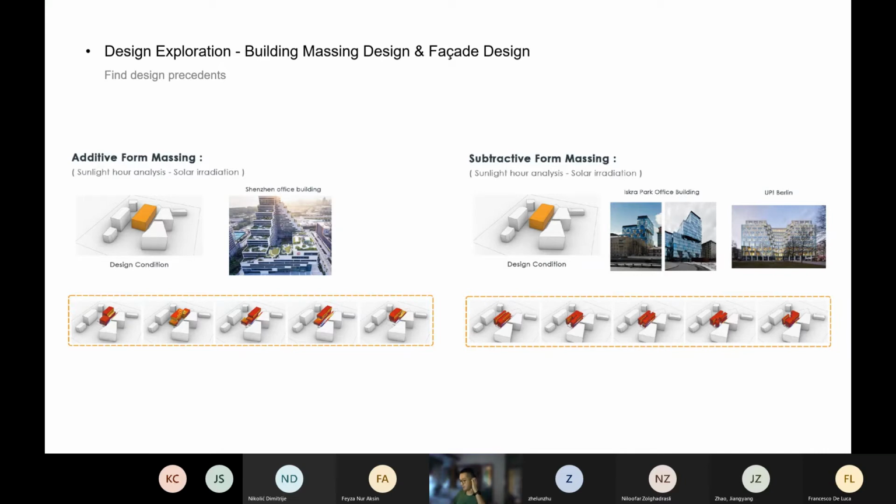In this one, the designer, a user of EvoMass based in Egypt, defined an objective function to maximize the sunlight hours on the eastern facade, because maybe the sunlight in the morning has a small amount of solar radiation, and also can provide sufficient natural daylighting, for some reason like this.